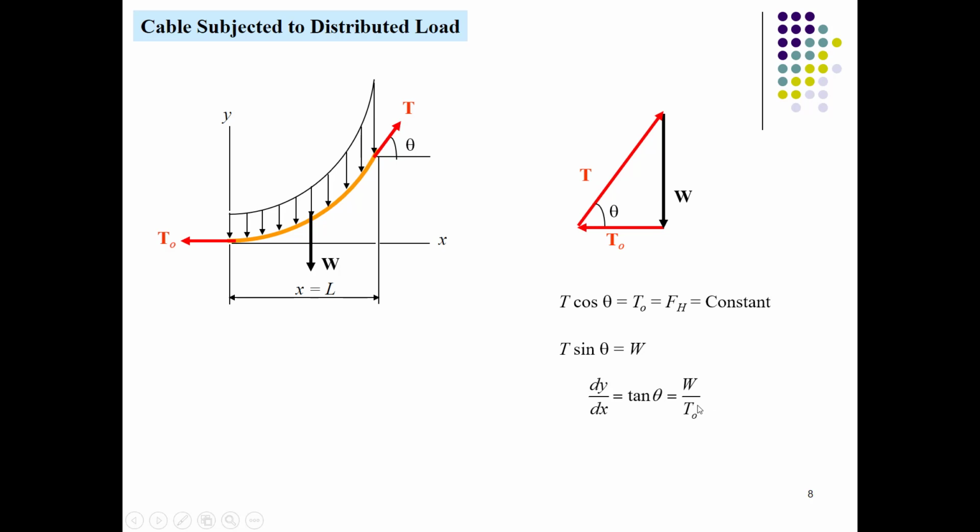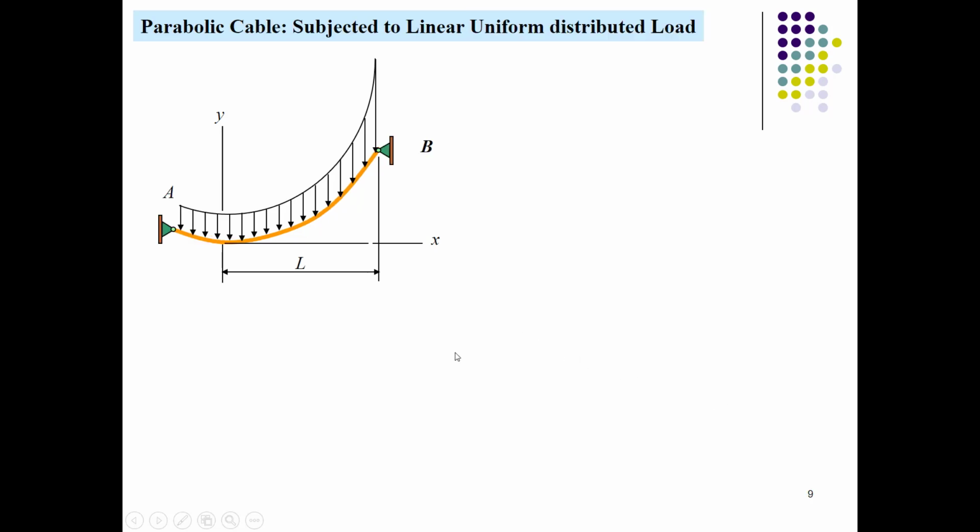Similarly, we have a cable upon which the uniformly distributed load is laid. We'll have to calculate the tension within the cable member. So first we have to calculate the W naught, which is the resultant force divided by horizontal distance, which is basically the uniformly distributed load. We'll take the section at this point.